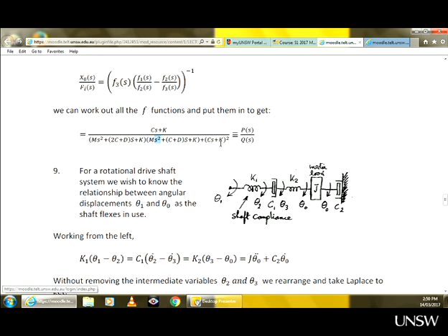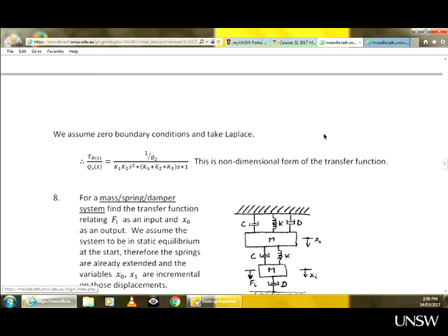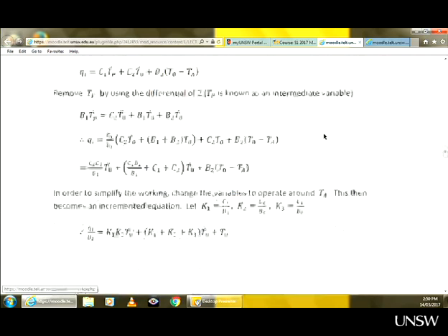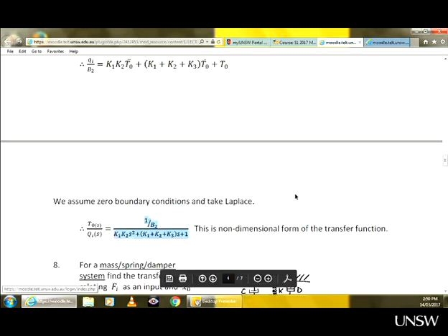The order of the polynomial in the denominator determines the number of time constants, at least in theory. Back here, this transfer function is of the second order, therefore 2 time constants. How many steady-state gains does this transfer function have? 1. And the value is,